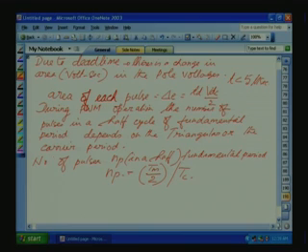Okay. And this number of pulses, if you see here, due to carrier period, whenever the sine touches the triangle, you have these type of pulses, small pulses.